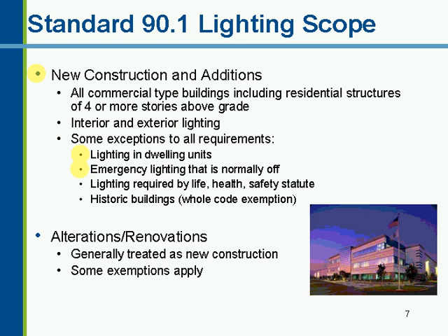Your typical battery-powered emergency lighting, of course, is exempted from compliance. If you have any life, health, or safety statutes that apply to the building, that specific lighting that's required by that statute would be exempted as well. And if you have a building that perhaps is on a state or national historic register, the lighting in that building and around it would also be exempted. There are lots of historic registers. Typically this means a state or national one, but if you have a local one, you may want to talk to your local building official and see if that would apply for an exemption as well.